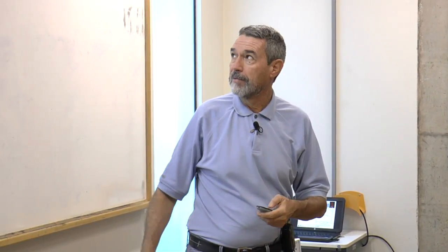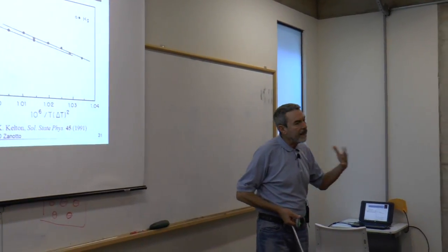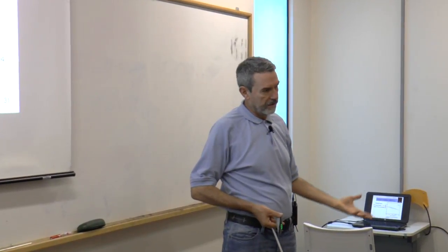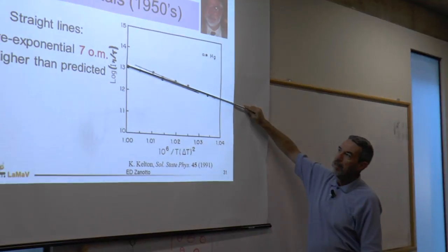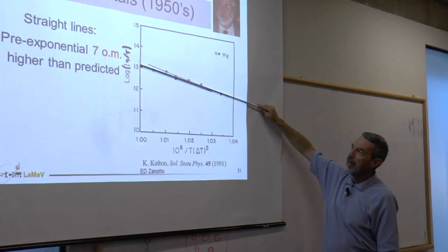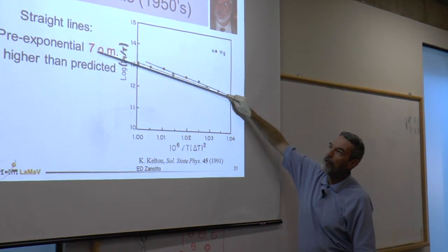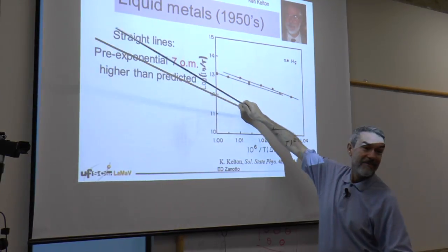However, let me go back. Remember, the nucleation rates were measured indirectly via the overall crystallization and crystal growth rates. Also, the range of temperatures was very narrow, only 2 degrees Celsius. So, if you follow this, any small error here, like if this real curve is like this, then the extrapolated value could be 7 orders of magnitude less.